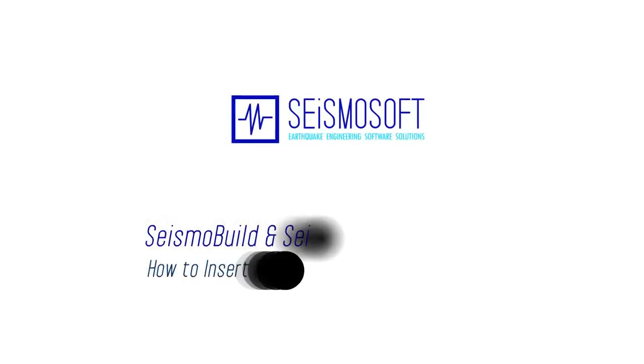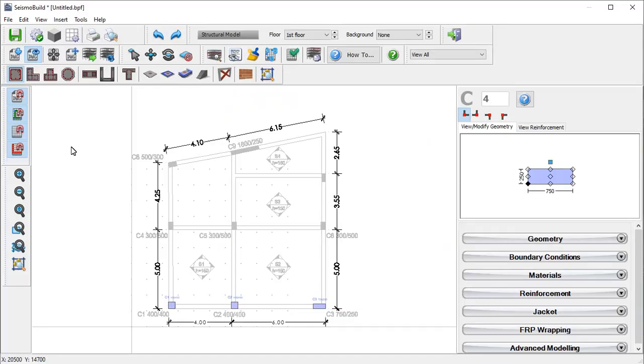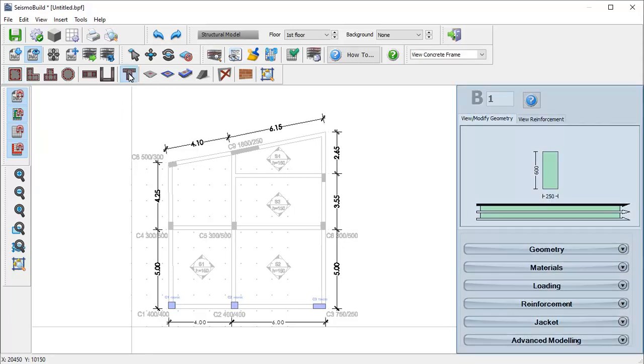This is a quick tutorial of how to insert a beam in SeismoBuild and SeismoStruct's building modeler. First, we will go and insert the beam elements by clicking on the Insert Beam button. Pressing the button will cause the opening of a window with details on the member section at the right side